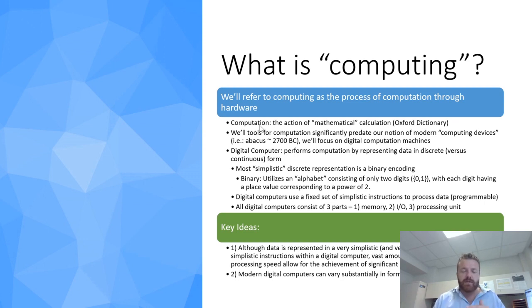If you only have 2 levels or 2 decisions that you have to differentiate between, it's a lot easier than if you're trying to store or transmit 4 or 5 levels. So a lot of times people don't get that the utility of storing information in 2 states, either ones or zeros, is really about providing noise immunity, because unfortunately when you store information or send it over a distance, it's always going to be corrupted by noise.